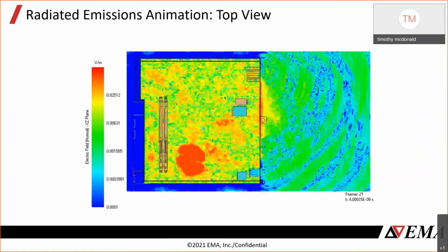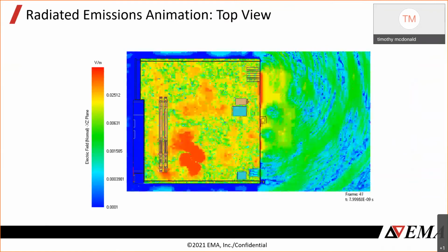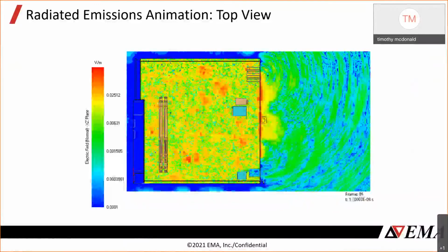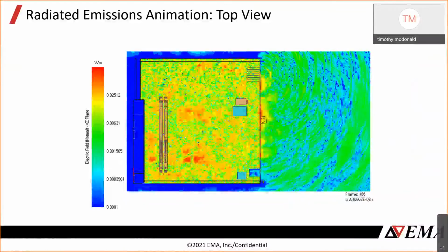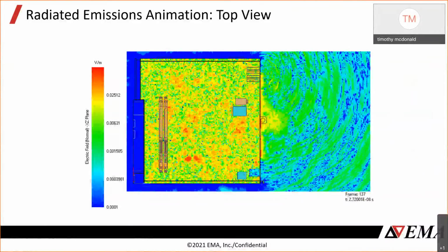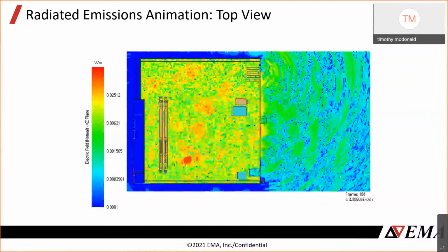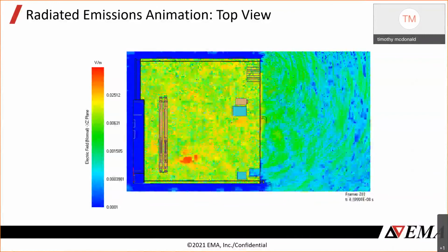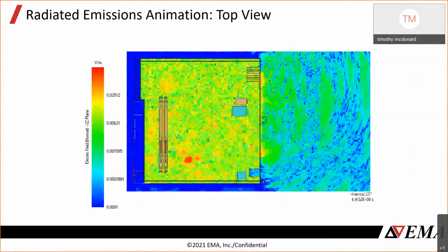And then we hit the simulate button, and this is what we get. We get the fields everywhere. So we've got the source from the Galileo board inside the enclosure, and that creates fields in the enclosure. And you can see very clearly this shielding of the enclosure means that the fields outside are much lower, and coupling outside goes through that seam that we specified.